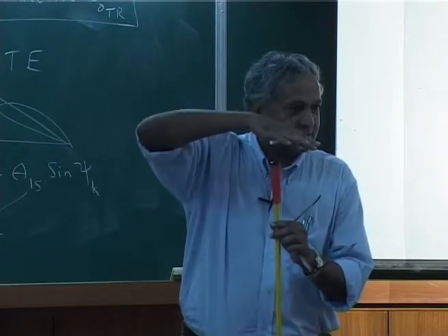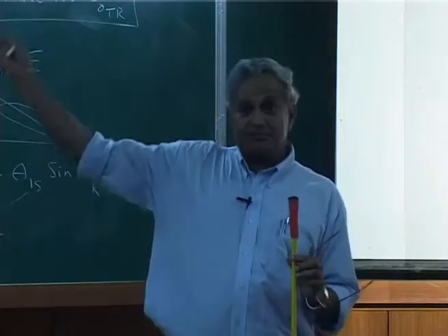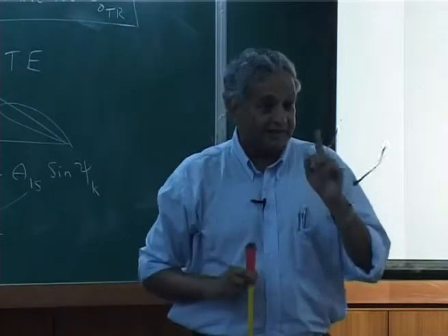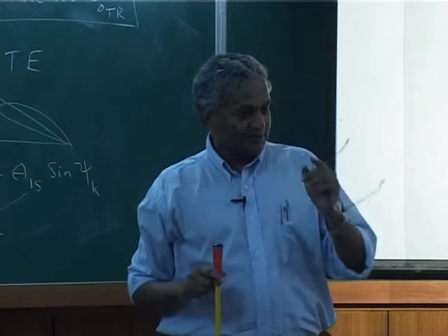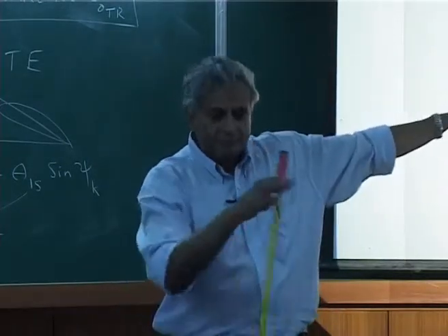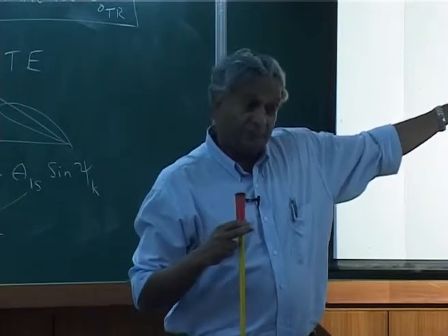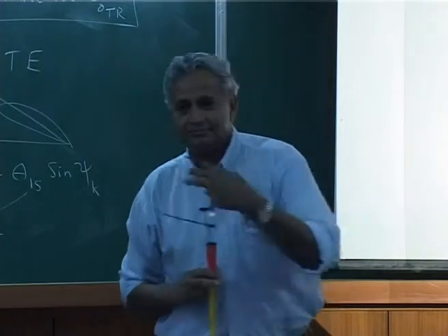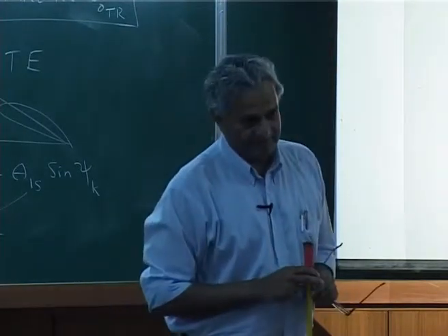That means rotor disc tilt happens because of the flapping motion of the blade. So, now you understand flap dynamics means the motion of the blade out of the plane of rotation is important. Only by controlling that is the helicopter flying.